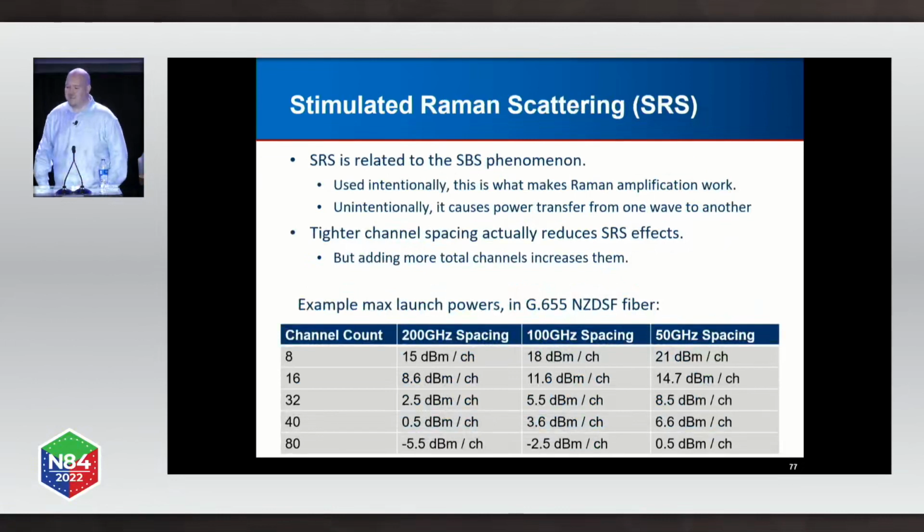So SRS is, remember I said how Raman amplification works. So when you use it intentionally, you get a good effect. When it happens unintentionally, what it does is it makes it transfer power from one wavelength to another. And the tighter you pack the channels, the more this occurs. So if you look at, for example, an 80 channel system, and you have them tightly, tightly packing them actually makes it better, which is weird and counterintuitive.